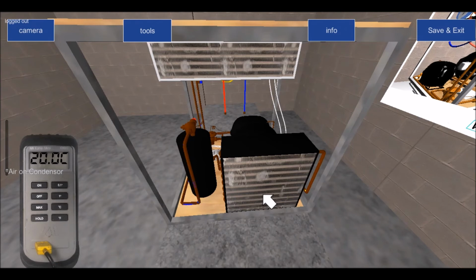Now, if we're dealing with the fluctuation, it can go as high as, so 25 plus 20 is 45. So it can go as high as 45 degrees and still be operating sufficiently, or it can go as low as 35 degrees and still be operating efficiently. In this case, it's at 40 degrees, which is midpoint. And as I say, the colder the air coming on, the lower my head pressure. The warmer the air coming on, the higher my head pressure.